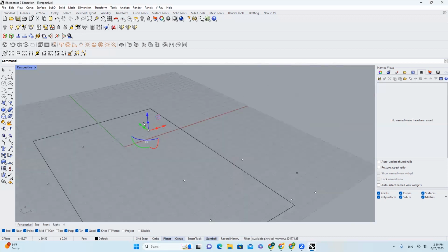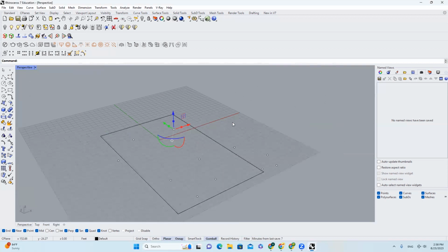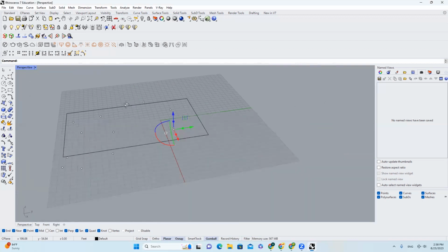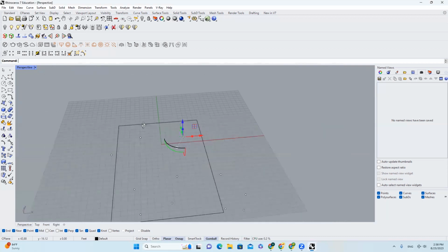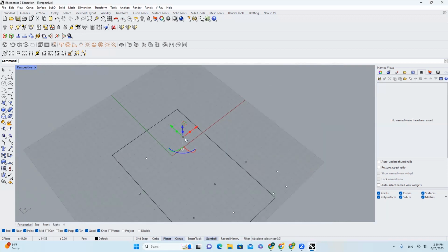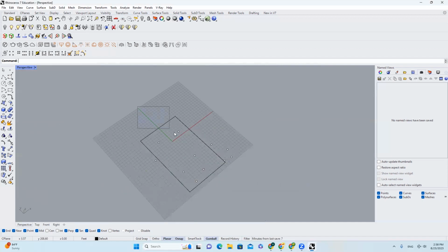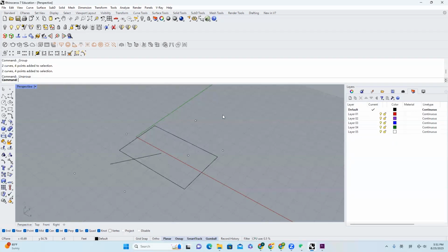If it's not, please remember to select the modeling aids gumball and rotate view around gumball. What this does is very straightforward. If you select this item, the gumball shows up, click your right key and move things around. You will make sure that your viewport will always focus or rotate around this thing that you selected, which is very important and handy.